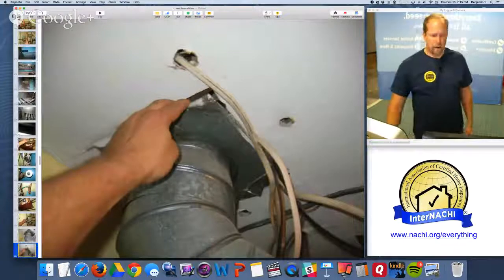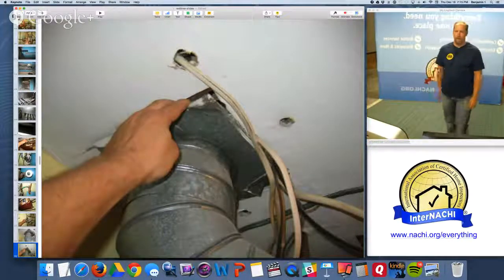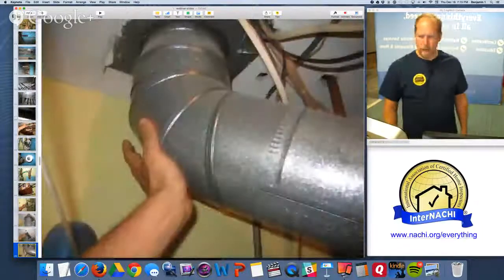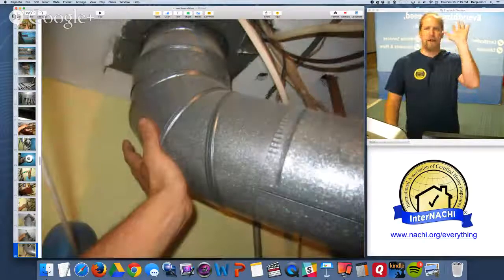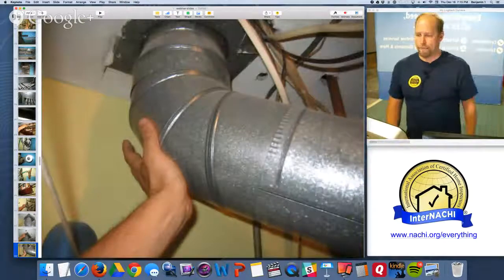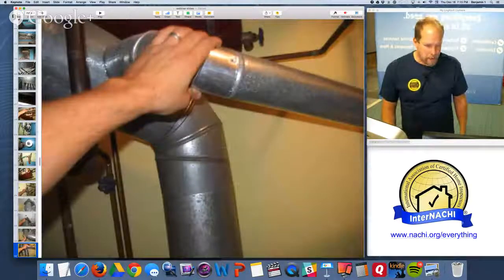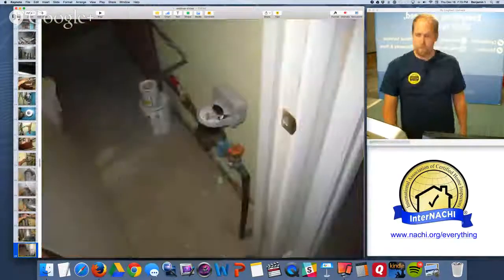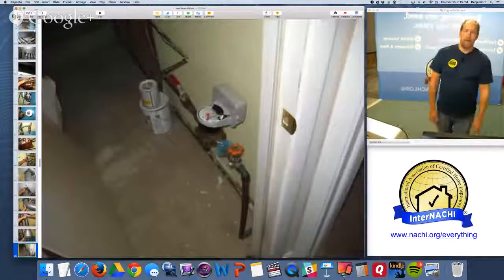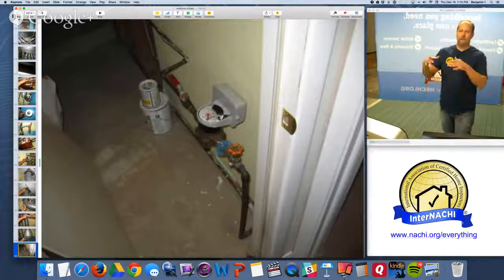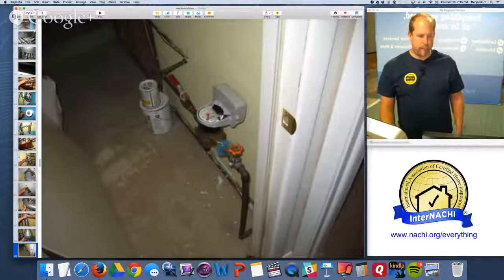The fire flashing is improperly installed. It's loose, very loose. The whole pipe was actually sagging a little bit. So it's sagging, I can push it up. There were no fasteners to connect the pipe connections together. It's shared with the gas hot water source, natural vent. So the heating system needs to be cleaned and serviced, and the flue pipe needs to be secured, and the fire stop flashing needs to be fixed.